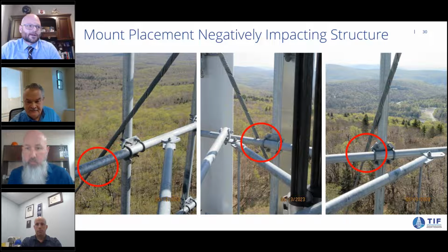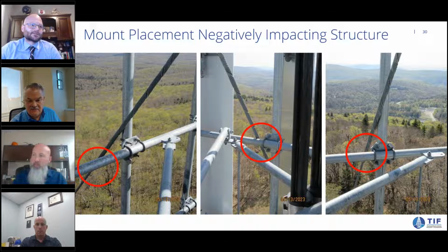Yeah, just real quick, guy wires move constantly depending on site conditions. In this one, the mount was installed up against the preforms for these particular guy wires. That'll rub and rub, causing damage over time. This is when you stop and escalate, because you don't want to fail your PMI. Ask your engineer, can I lower these mounts by 6 inches and move forward? Exactly.